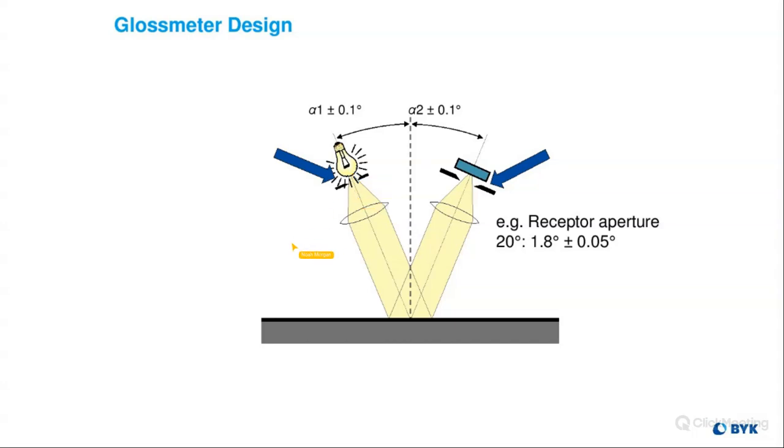With this light source, you need to have a specific sized aperture, and same with the detector, that only allows a specified amount of light to pass through that hole, which then goes to a lens, which then focuses all that light to a certain spot. And then on the same end with the detector, when that light comes back, it needs to hit this lens and go through that defined aperture again.